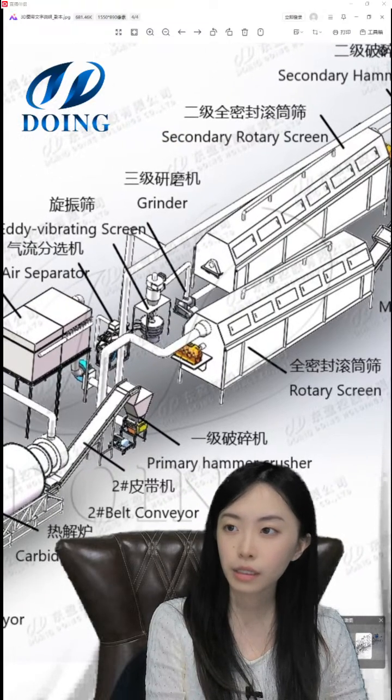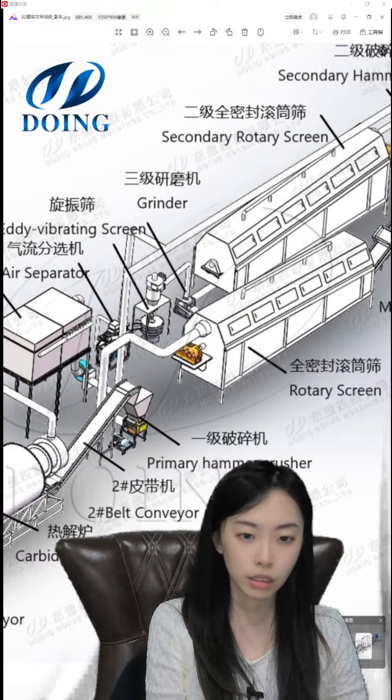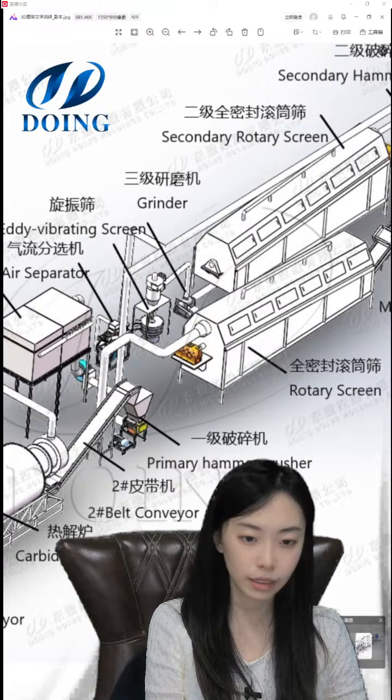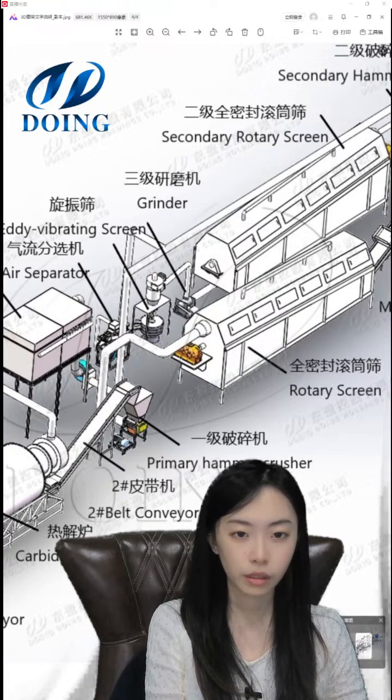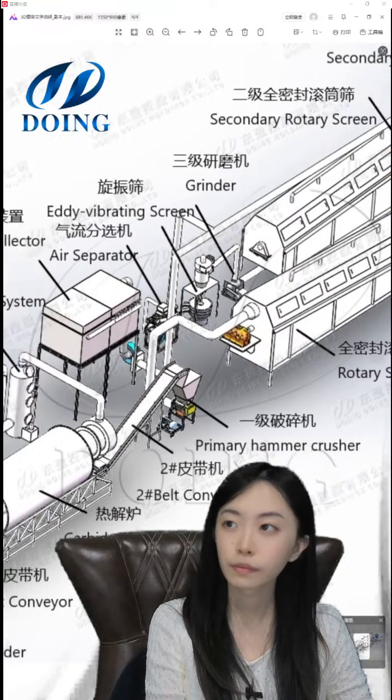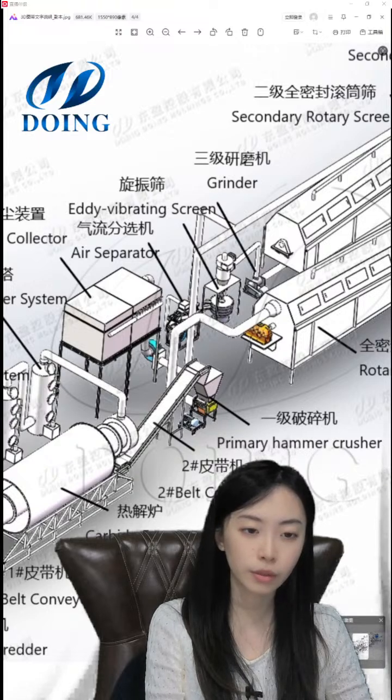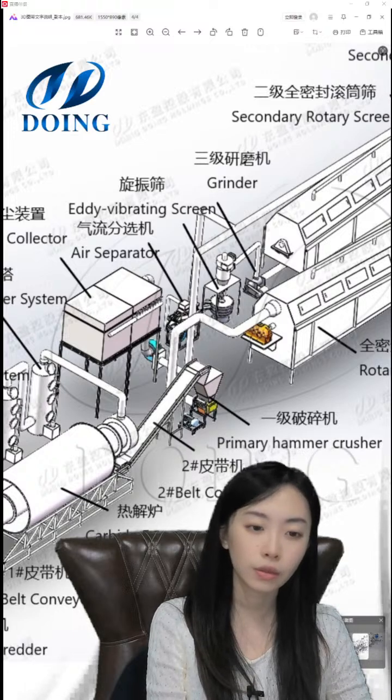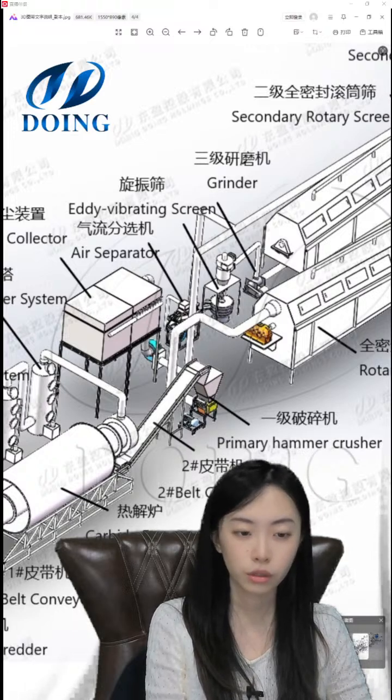And this is the grinder. With the grinder, we control the sizes of the particles. It's used to grind the raw materials into granular sizes. Then the ID vibrating screen will collect most of the powder, 99%. The advantages of it are low noise, high efficiency, and a fully sealed structure. So it separates the powder and particles, and recycles the black powder to 99%.